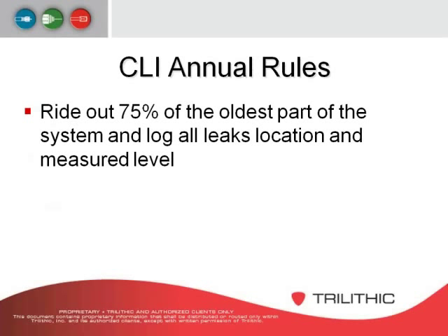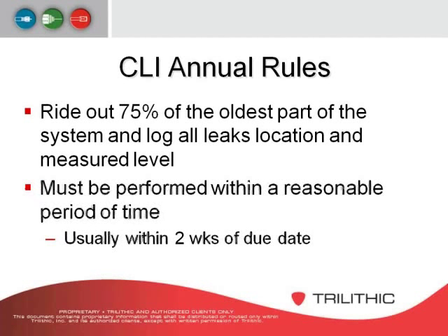Now the annual rules. What the FCC wants to see annually is drive out 75% of the oldest part of the system, and log all leak locations and the measured level. We'll talk about how to properly measure the levels for a signal leak when it's turned into the FCC.